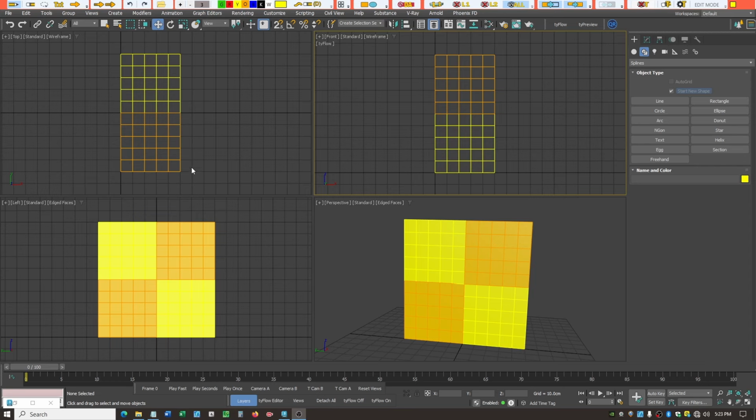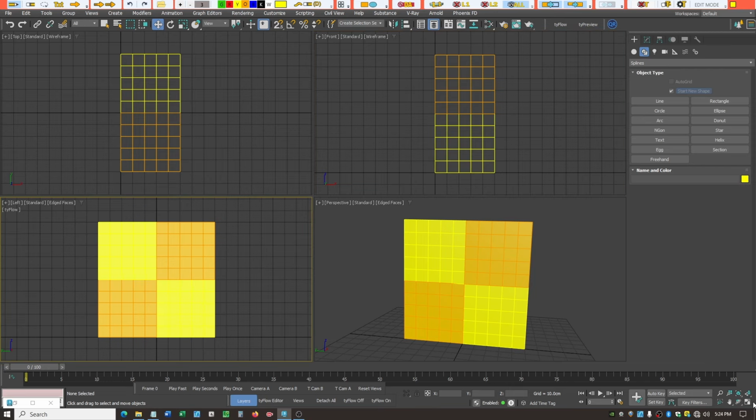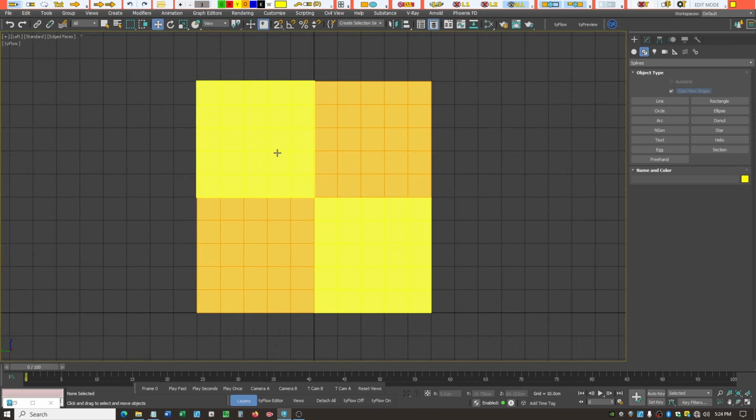When we're making curves, we're going to do them from the top viewport. So left hand curves, right hand curves, whatever, will be created in the top viewport. When we're making straight sections, we're going to do them in the left viewport. So let's pick our left viewport and maximize it. For this section, we're just going to make 2 straight track segments.